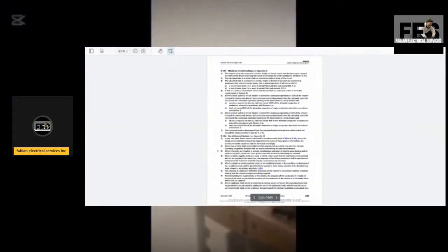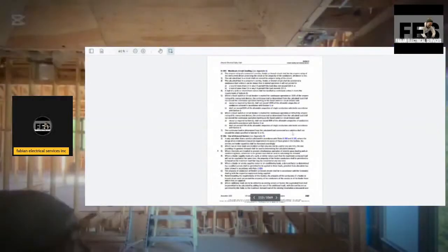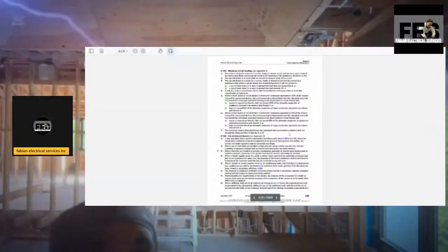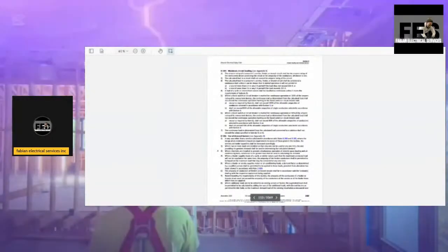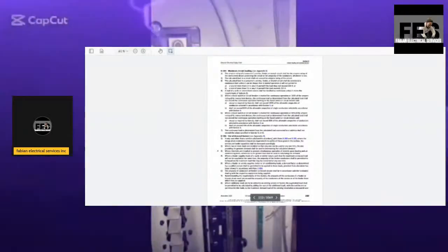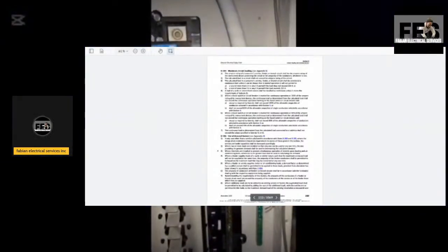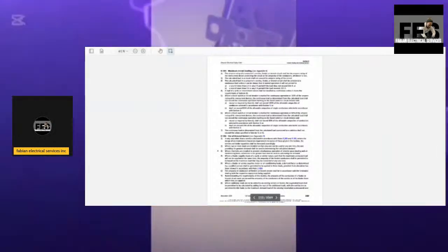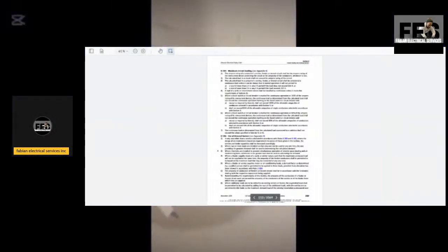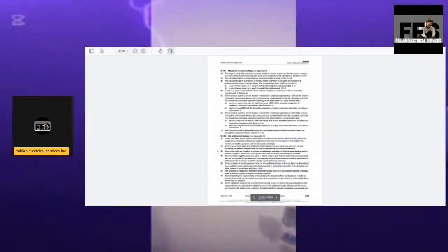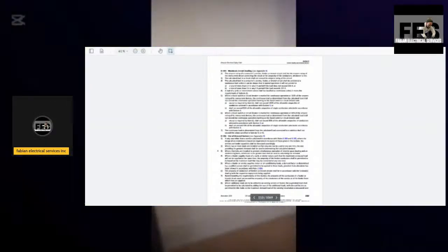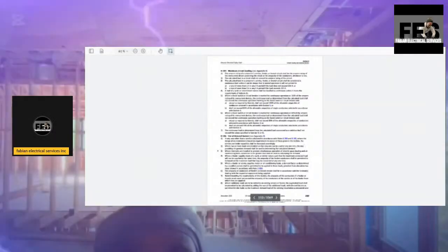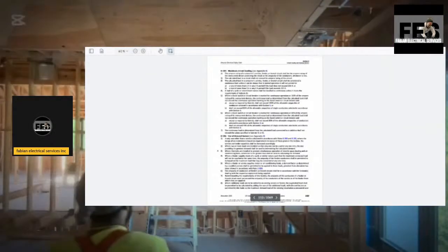The continuous load as determined from the calculated load connected to a cable bus shall not exceed the value specified in subrule 5 or 6. Use of demand factor in any case other than a service calculated in accordance with Rule 8-200 and 8-202, where the design of an installation is based on requirements in excess of those given in this section, the service and feeder capacity shall be increased accordingly.